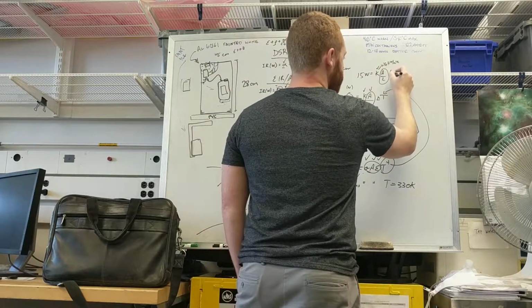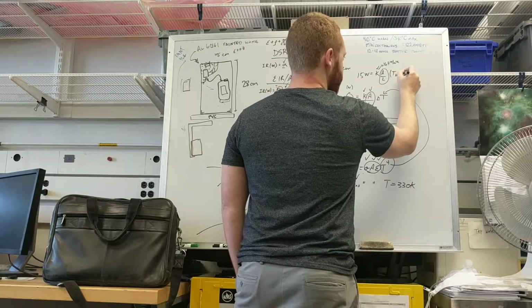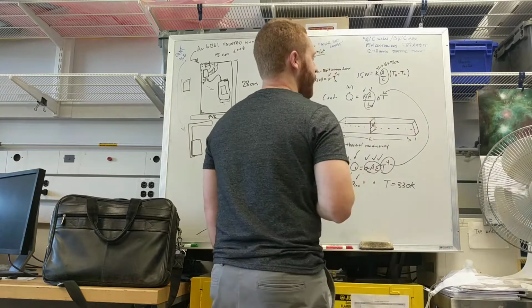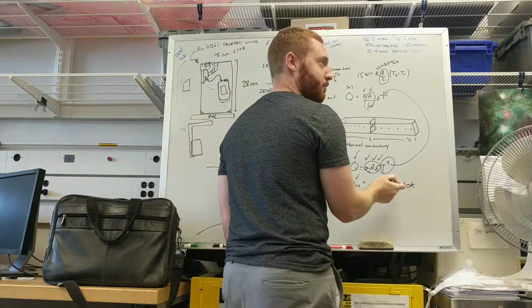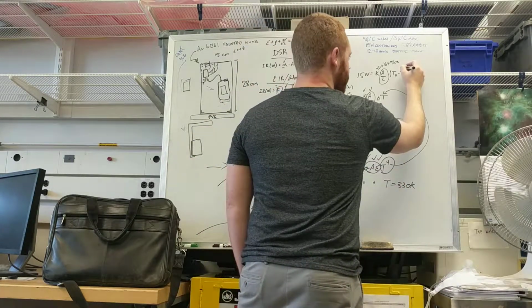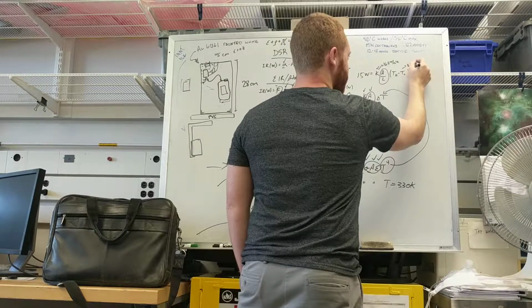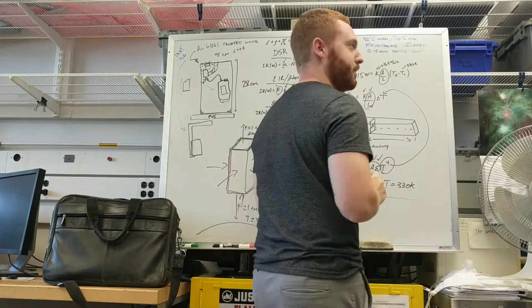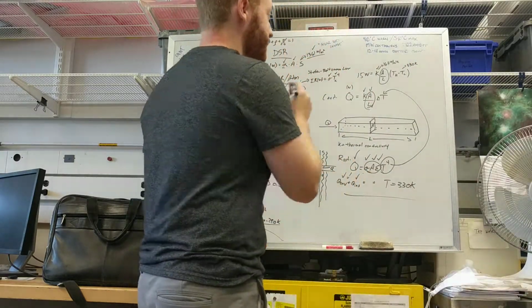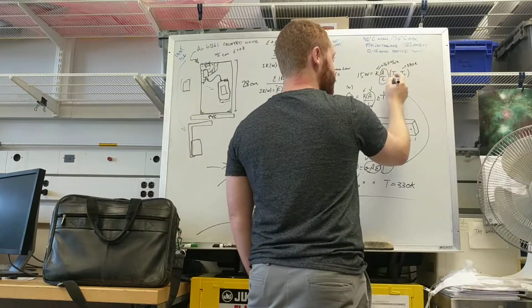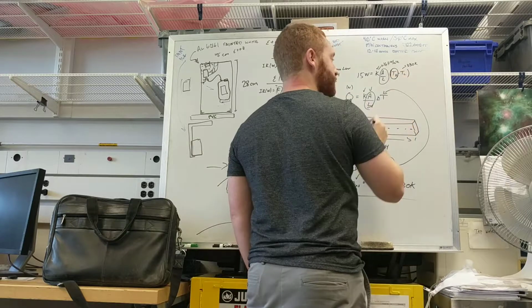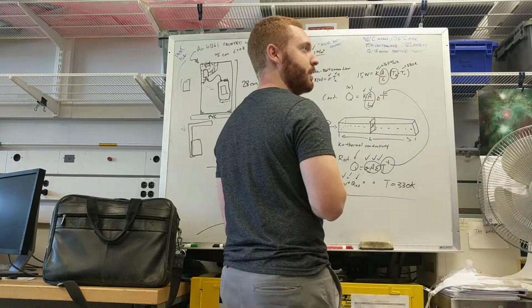And then you do temperature high minus temperature low. You know that the electronics have to be operating at a warmer temperature than the heat sink. So you know that your temperature low is now 330 Kelvin because you did your radiation analysis, right? So now what's the only unknown? Well, you plug in some values, and you can find the temperature of your electronics, denoted by TH.